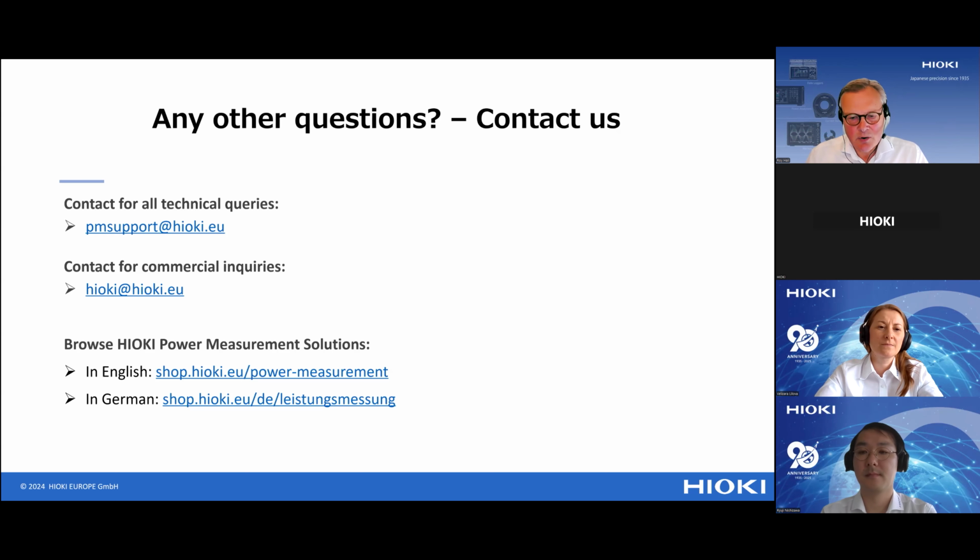Also, the current sensors and the power analyzer can communicate with each other, and therefore solve issues like time delay of the current sensors and compensate for that. That's a very big advantage, especially when you are going to measure high current and high frequency applications, like, for instance, an inverter measurement, or the loss of an inductor or a reactor. Okay, thank you, Roy.